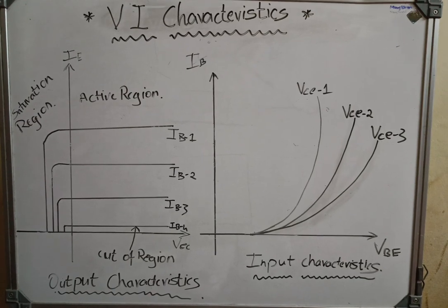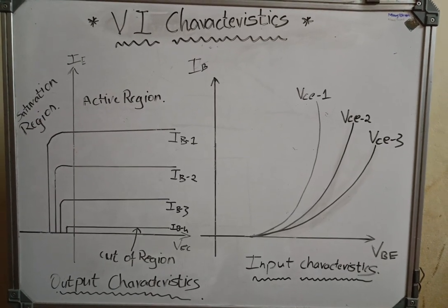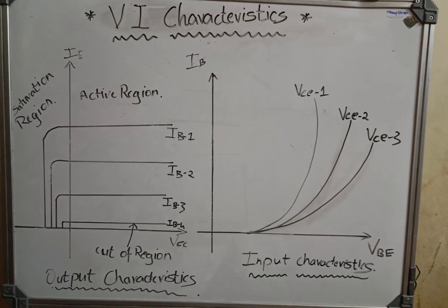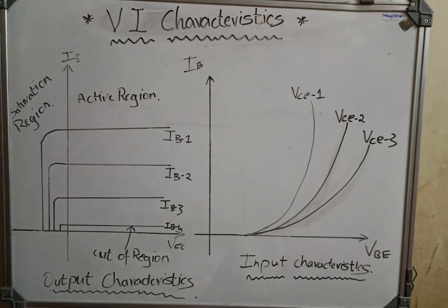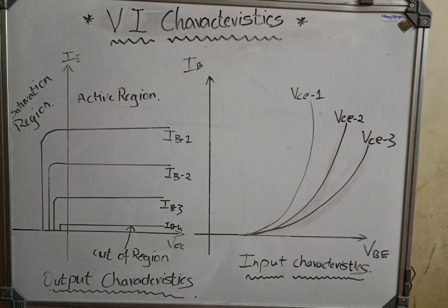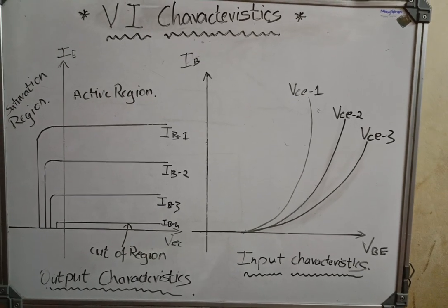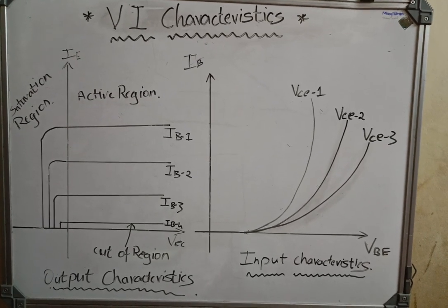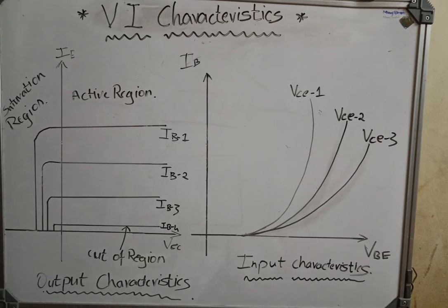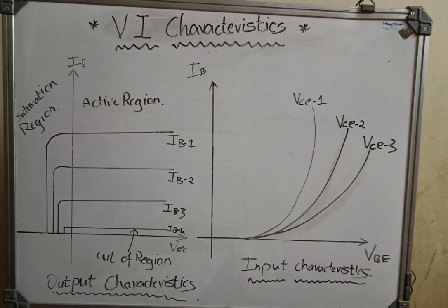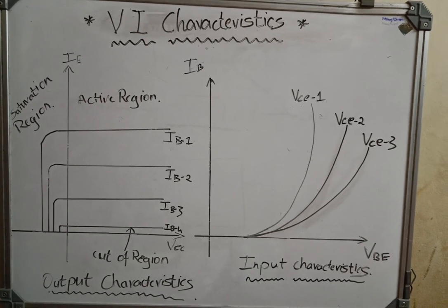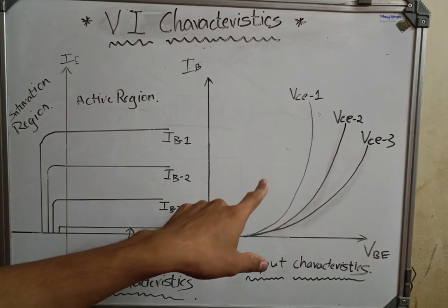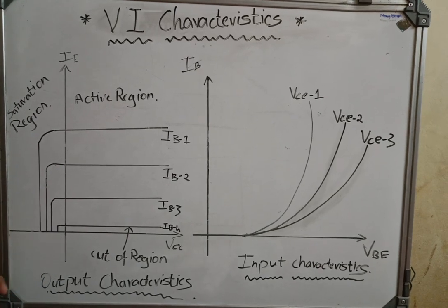In physics, the graph representing the relationship between the current and voltage of any transistor of any configuration is called the transistor characteristic. In this section, let us learn the transistor characteristics in detail. Any two-port network which is analogous to a transistor configuration circuit can be analyzed using three types of characteristic curves. They are input characteristics, output characteristics, and current transfer characteristics.